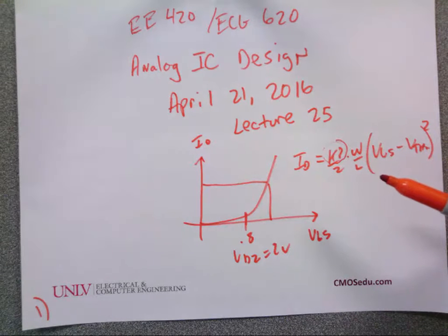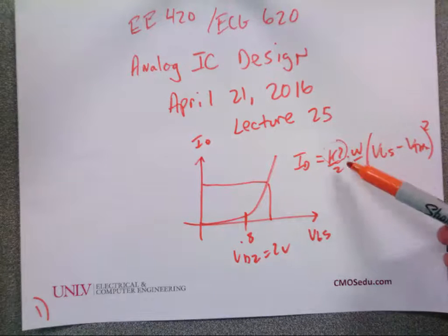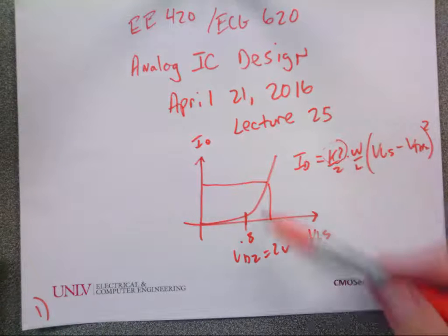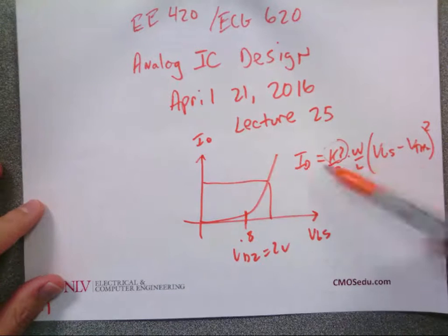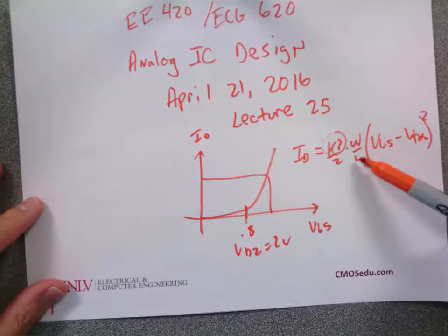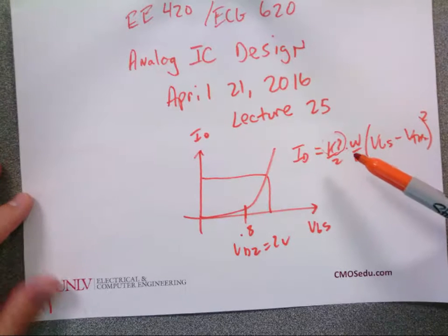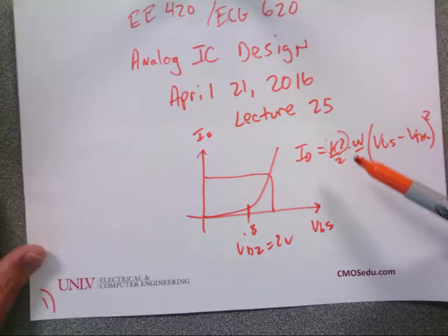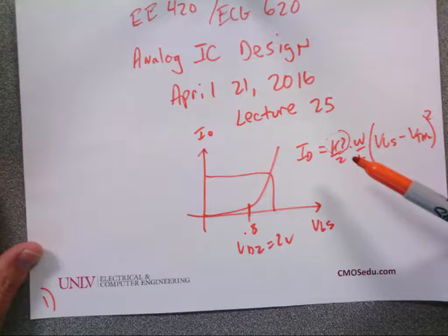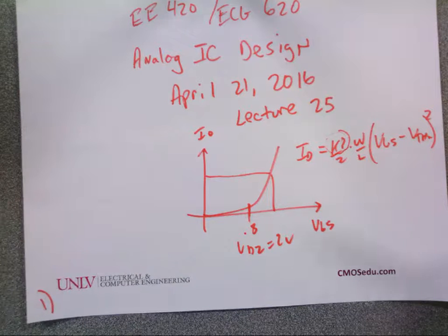And then, would we similarly want to do a table with your KP values? No, I don't think you want to do KPs, because when you change the sizes or the VGS, and you solve the same exact equation with a different VGS or a different size, you're going to get a different value for KP. I think that's an issue. Well, this is a real process. It's not the old 5 micron, 10 micron minimum channel length. So it makes sense not to have a standard KP. That's why I didn't do it in the book. That's why I did all those sims at the end of chapter 9.